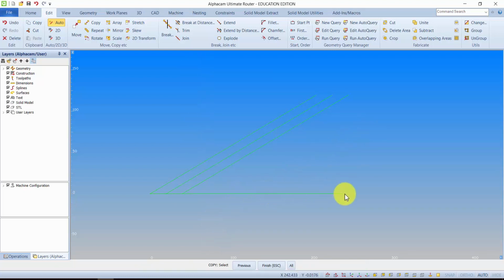If you remember as well, we also need a line starting at the right hand side over here, going at 60 degrees to the left. Let's use our same trick. Rotate this line about this point, and you'll just have to make sure you get the proper angle. It's not actually 60 degrees because you can see the way it measures the angle with respect to the extreme eastern point, the right hand point. So it's actually going to be 300 degrees in this case. So type in 300, enter. How many do I want? 2, enter.